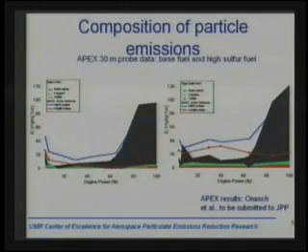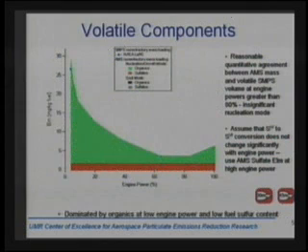And so just schematically, we can look at it this way: the sulfate contribution is more or less constant across the various powers. It shifts from the nucleation mode to the soot mode as we go up in power, but the total amount doesn't vary so much, whereas the amount in the organic contribution changes dramatically. It's very large at low powers where the combustion inefficiency drops off. Still, it's a highly efficient engine, but it's not as high as it is at high powers. At high powers, the combustion efficiency is very high, and we have very little organic contribution. It doesn't go away entirely.